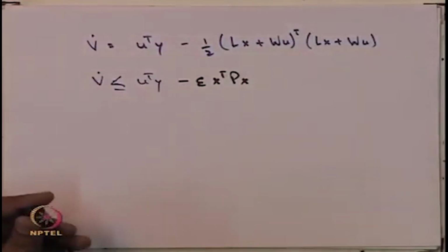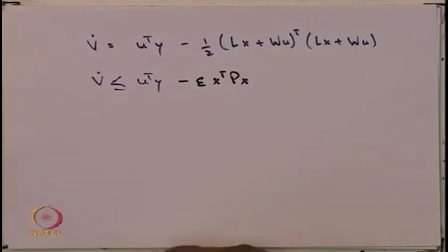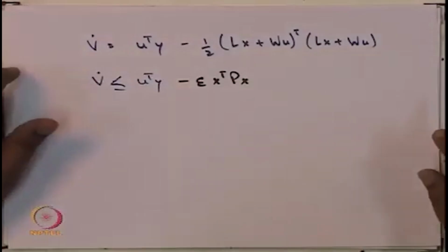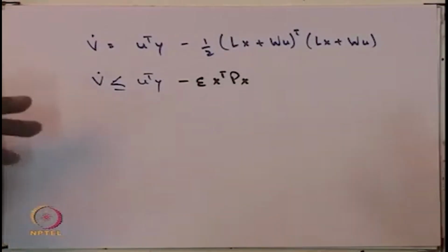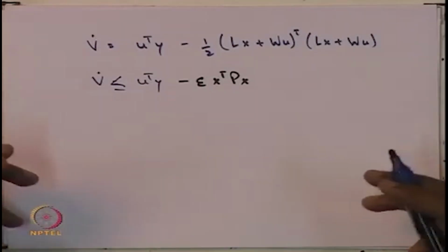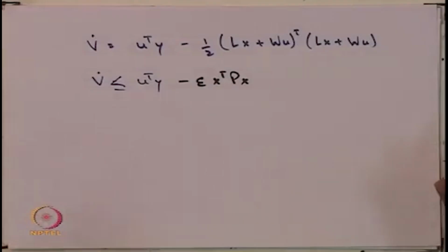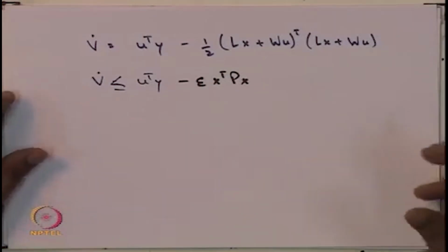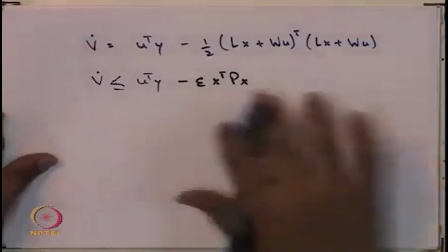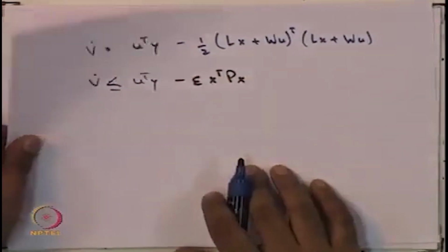Now, what I am going to do is make use of this rather powerful theorem, and look at all kinds of nonlinearities and derive new results about which nonlinearities, when put in a feedback connection with a certain kind of linear plant, would result in an asymptotically stable system. Okay. So, let me conclude about this first.